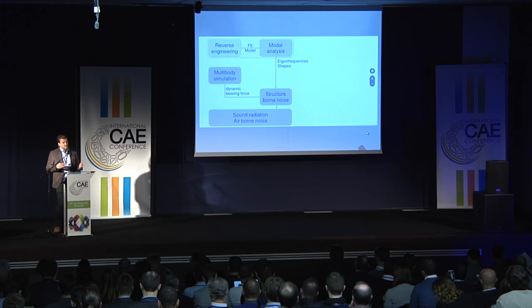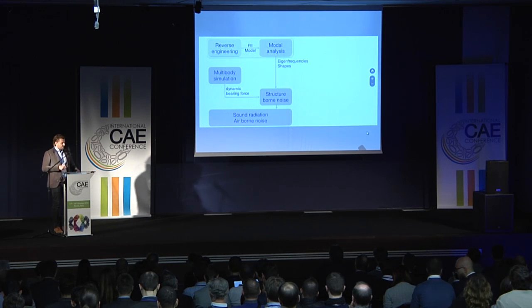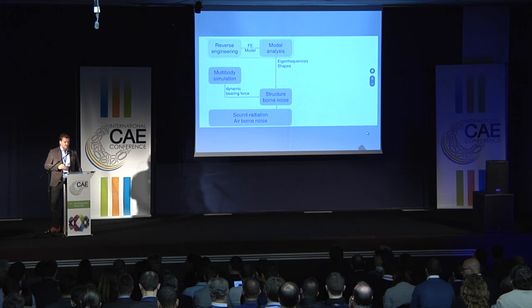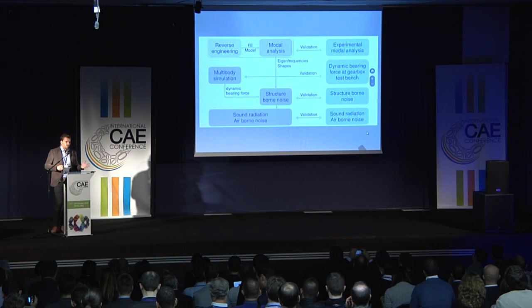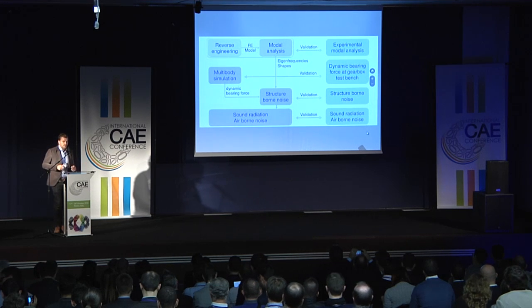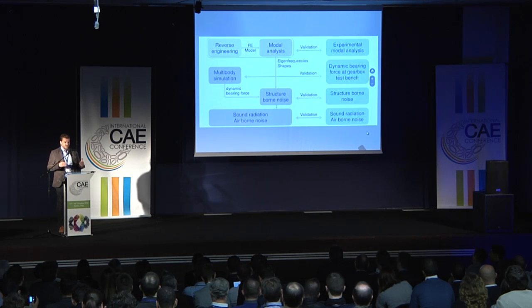And if you have the velocities, you can easily calculate the sound radiation of your structure, in this case the gearbox. One of the best parts of this calculation chain is that we can validate every calculation step with a measurement. For modal analysis, as you know, experimental modal analysis. For the multi-body simulation, we set up the test bench. And the same happens for structure-borne noise or sound radiation with microphones, as you know.